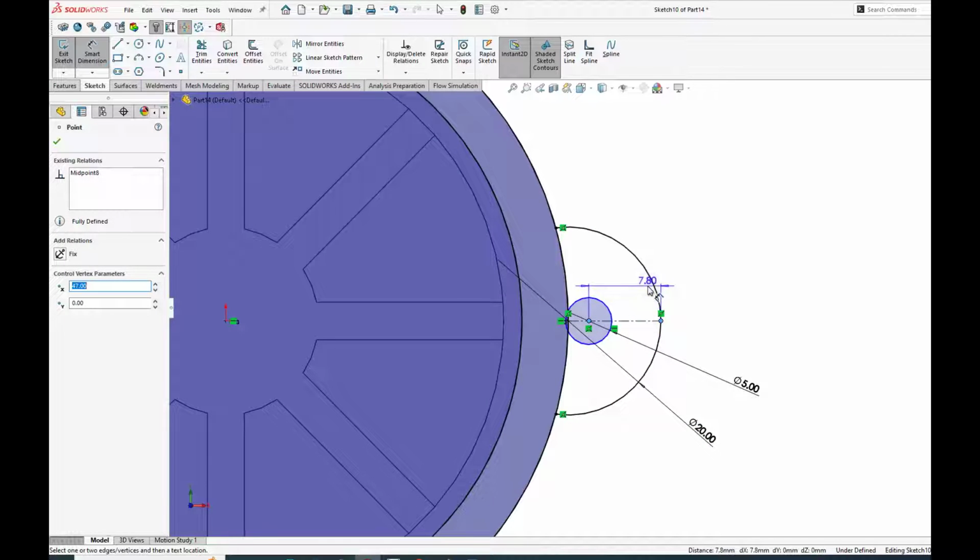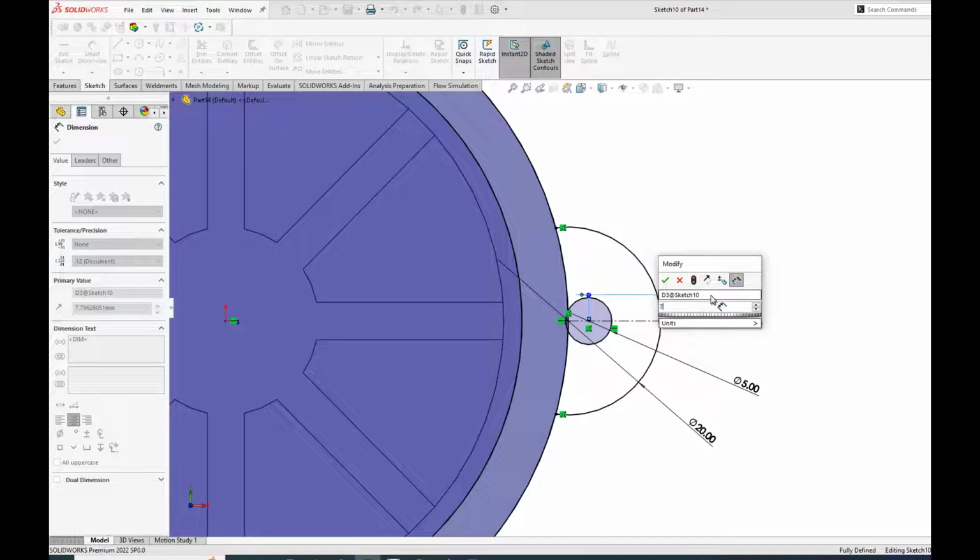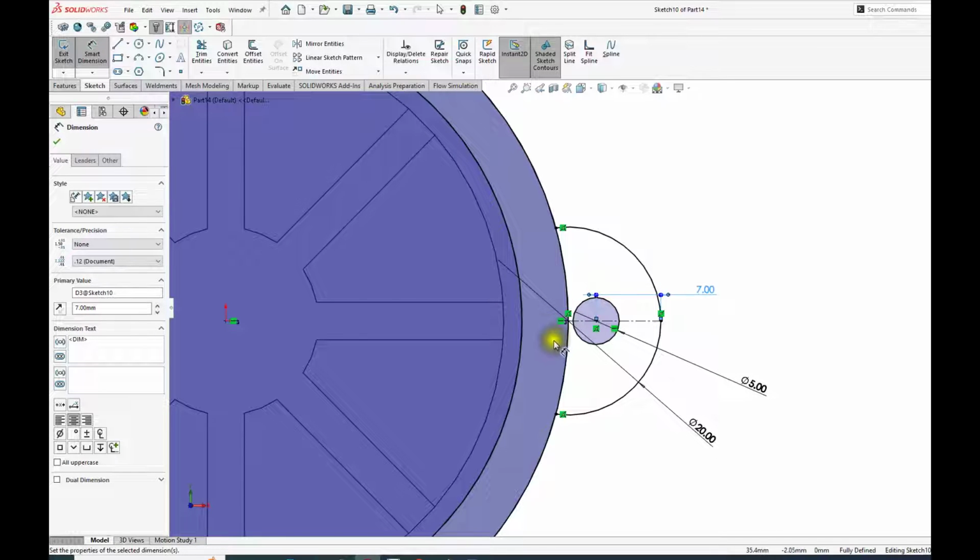That distance could be a good 7 millimeters, so it's not touching this part here. I don't want to mess with the casing. It should be out of the casing but strong enough, because this is going to be PLA and it has to have 4 millimeters. It's always good to have a distance of around 4 millimeters between this here and here. 7 is because it's from the center. All right, it looks good now.